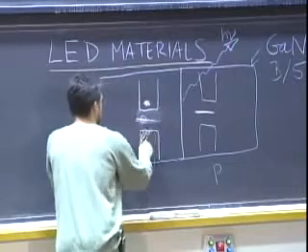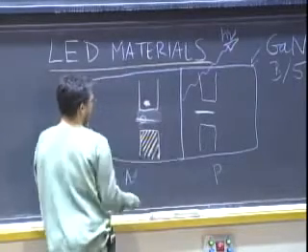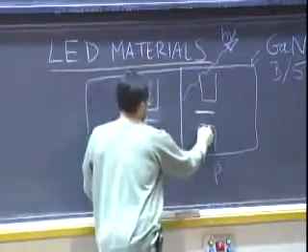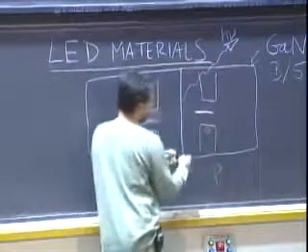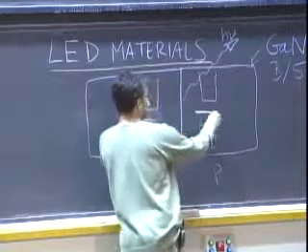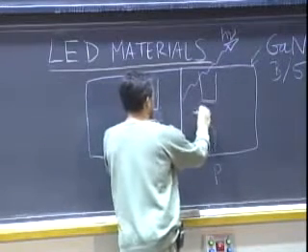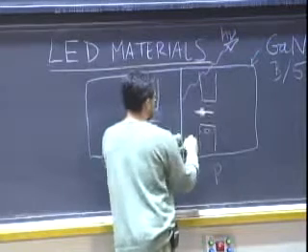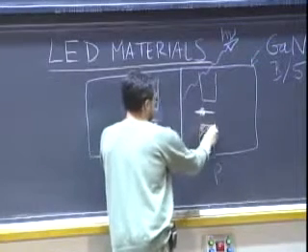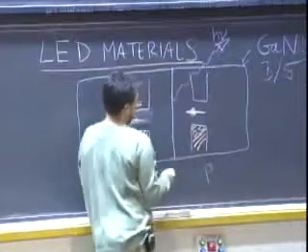And down here, we have our valence band all full. Over here, similar, except our material starts out with a hole down there because the electron has jumped up onto the dopant atom and become fixed in space as a negative charge, and that left behind a hole in the valence band down there like that.